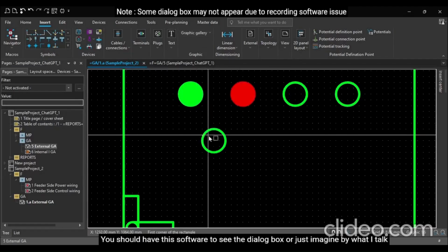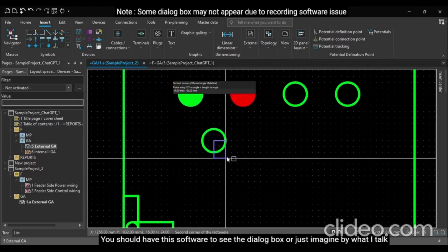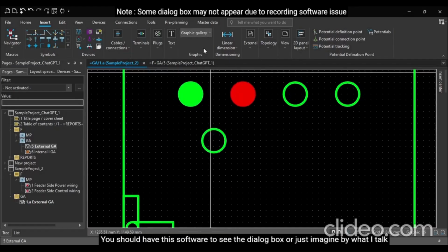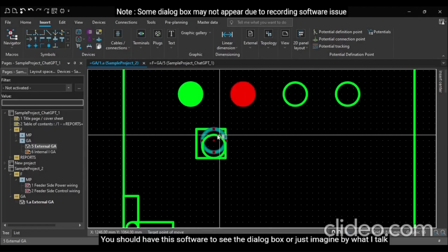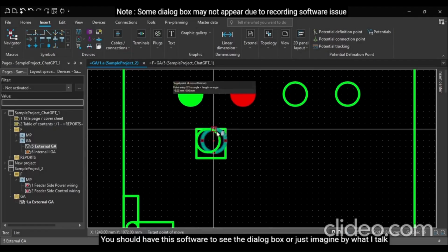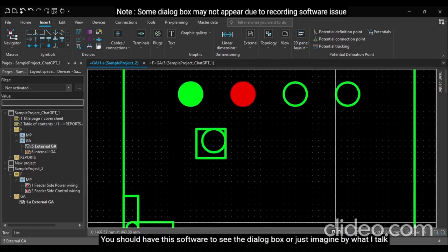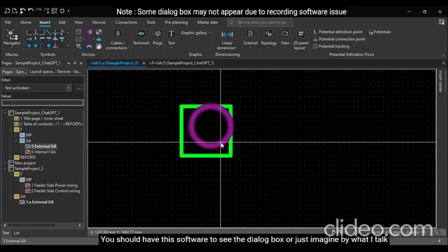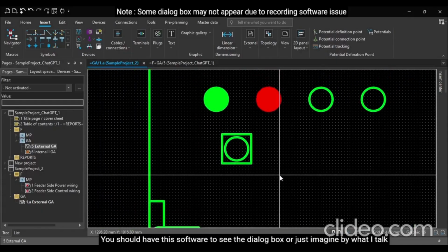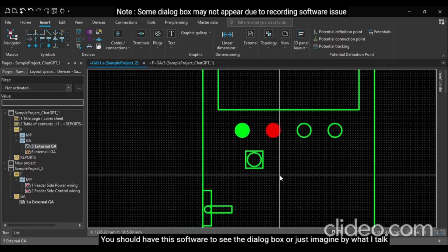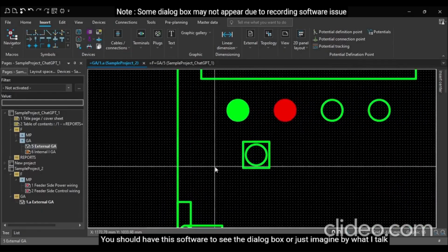So you'll need to remember shortcuts. Okay, without shortcuts you cannot perform EPLAN. So now it is not going on grid. Okay, any of the grid. What I'll do, I'll change the grid size. I'll change it to 4 mm. Okay, this is not an ideal practice, to change the grids. Okay, I'm just giving you an idea how you can do this.